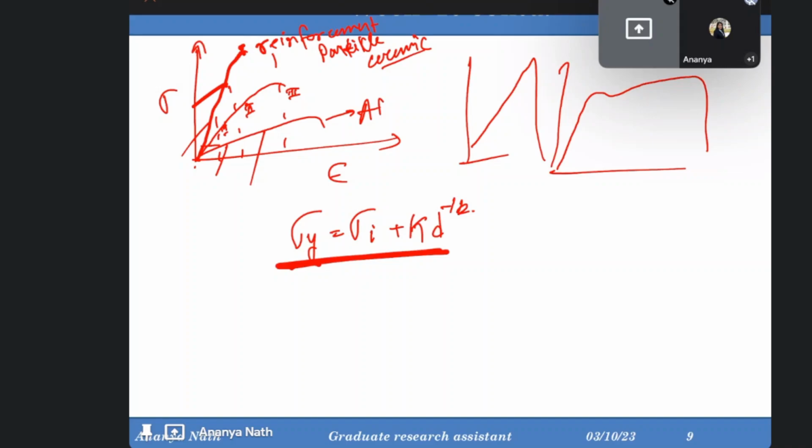So yes, the grain size, the relationship of Hall-Petch, everything is correct, but they can work up to a certain limit of the particle size. Beyond that size, if you are going for the nano level, they will act differently or adversely, to be honest, and the effects are very different than what you are expecting.